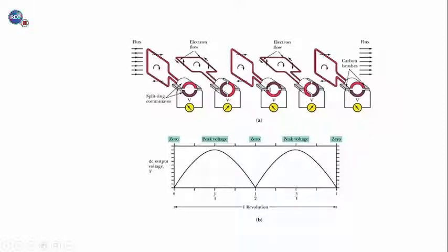Now at half of a revolution, that's when the brushes are at the gaps of the commutator, and as the coil continues to rotate, now the red part of the commutator is connected to the left brush. And so now this part of the coil that's on the left now, as it moves up through the flux lines, the current is going to be induced out of the page.